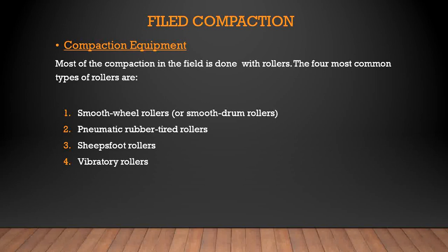The addition of water to the soil is normally done either during excavation or transport and nearly on the construction spot. However, water must be added before excavation in the case of clay soils, and if the soil has more moisture content than is required for proper compaction, it has to be air dried after excavation and compacted as soon as the desired moisture content is attained.